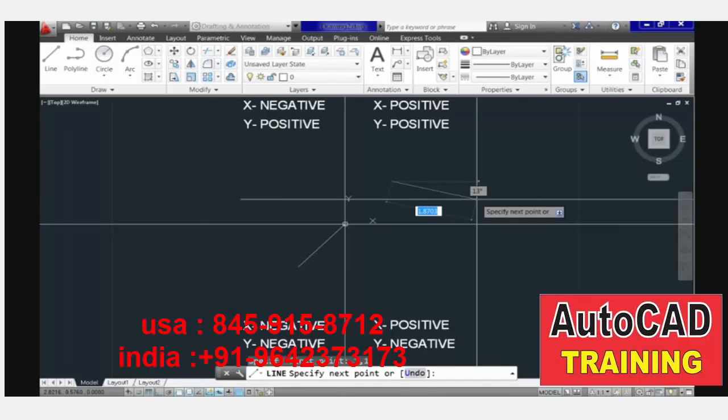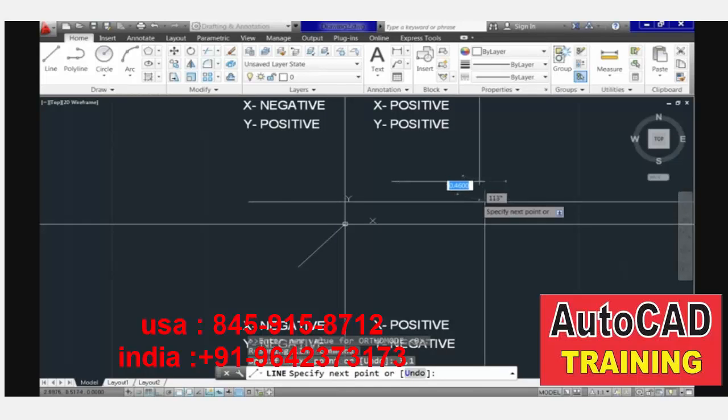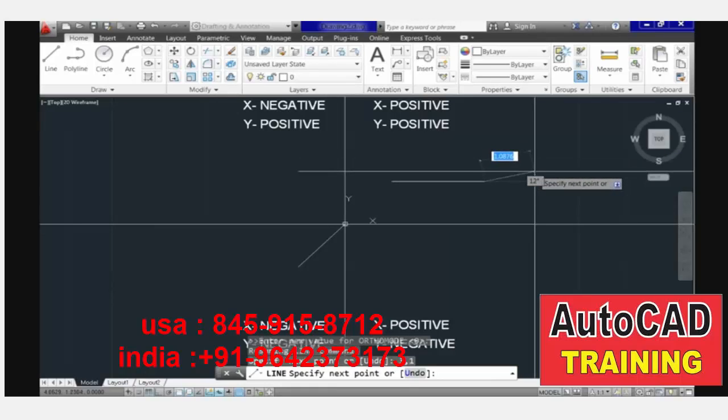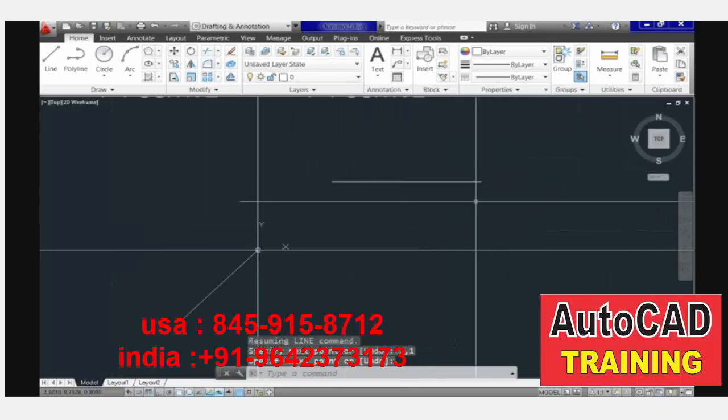How can I do that? Okay, first of all, I told you that the number symbol is associated with the absolute coordinate system. So you choose the number symbol and then the values. In this case, I use 3, 1, which means 3 in the x direction, 1 in the y direction. And actually, that means that based on the 0, 0, or our origin, it is 3 and 1.